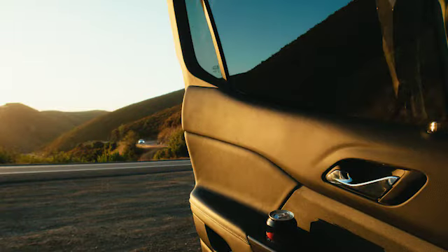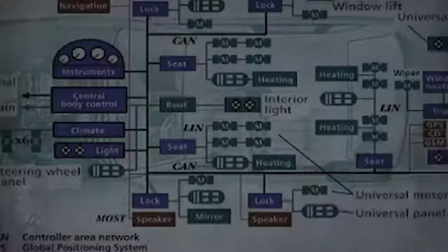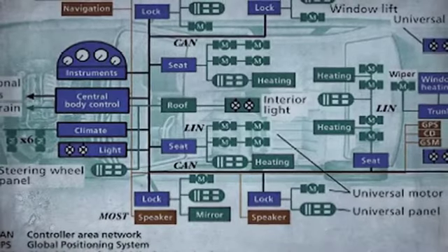In the past, you'd have door locks that when you pressed to unlock all the vehicle doors, there was a wire that went from that button to every single door. For each new component you add, you'd have to add more wires for everything it wants to talk to. This can be a lot of wires, it can add a lot of weight and a lot of cost to a vehicle network. To reduce this, auto manufacturers came up with a bus network.